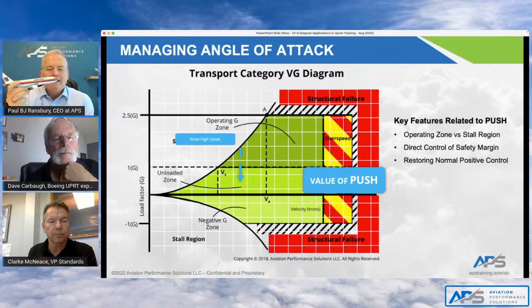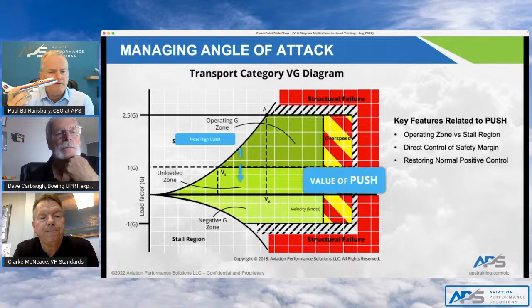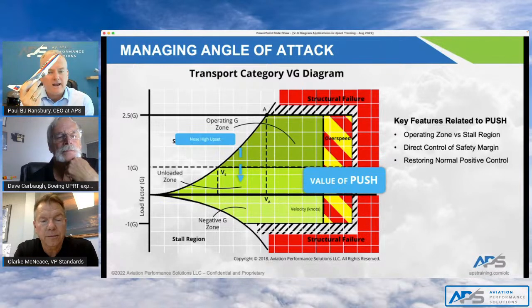Just love it. We're going to be in a situation now, for whatever reason, runaway trim, pilot distraction, maneuvering for traffic, maneuvering for terrain, where the airplane gets to a nose high flight attitude. And depending on the thrust setting and the altitude, this can be a situation of very rapid decrease in airspeed in this particular airplane. We're going to take a look at how quickly things happen in the VG diagram a little bit later with a video of a UPRT IOS.